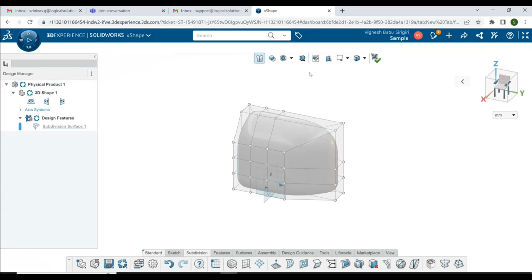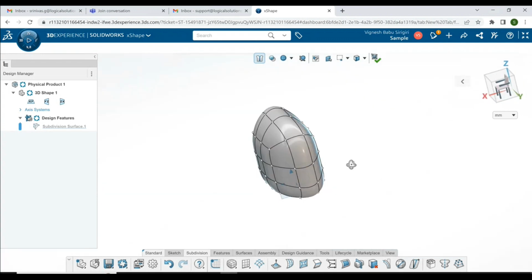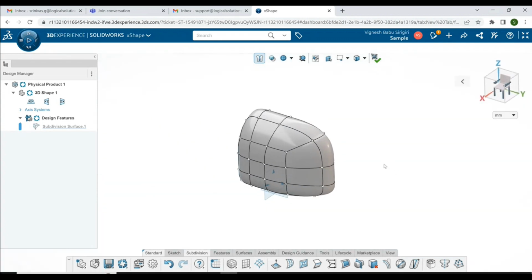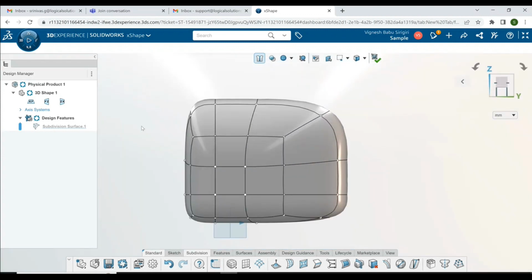Now I'm going to remove this cage and I'm simply showing the surfaces only. You can see here this has been created in this way. For the view orientation purpose, we generally use spacebar in SolidWorks. Similarly, we can use keyboard option G as the view orientation. Now I'm going to click on the keyboard option G, and I'm simply selecting this space to appear normal to my screen.